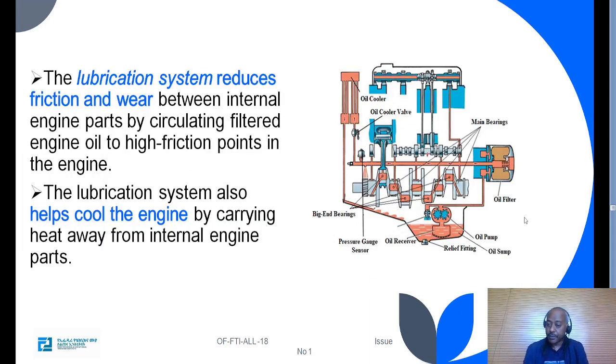The lubrication system reduces friction and wear between internal engine parts by circulating filtered engine oil to high friction points in the engine. The lubrication system also helps cool the engine by carrying heat away from internal engine parts.